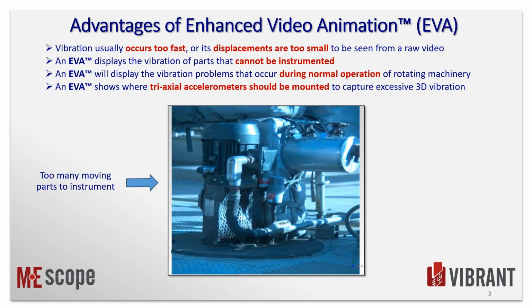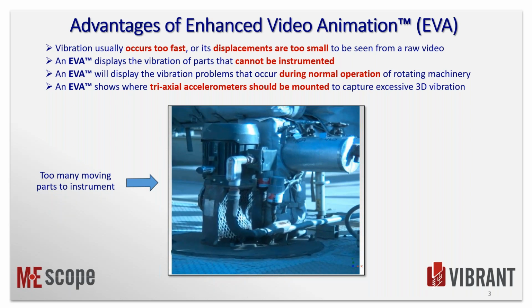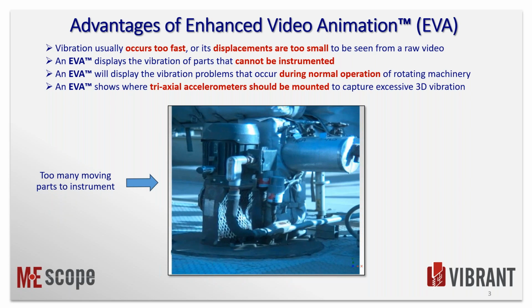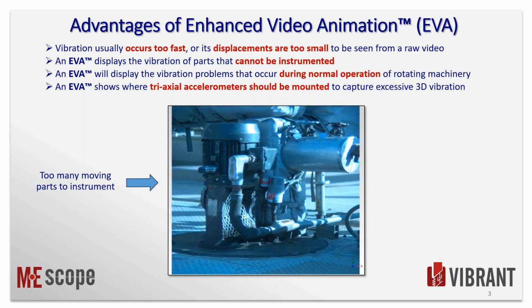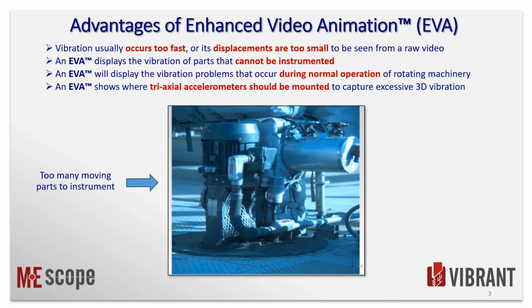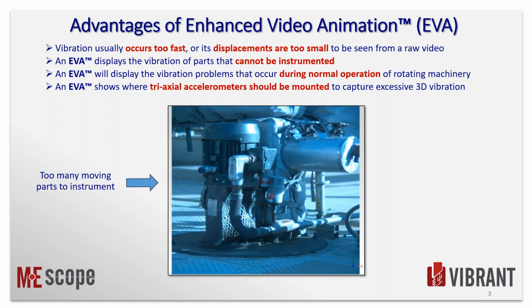And I'll talk a lot about ODS, operating deflection shape. What we mean by that is as soon as I have motion at two or more points and directions, we call them degrees of freedom, on any vibrating test article, we call that an ODS, because now we have a measure of the relative magnitude and the phase between two or more points on the structure. So we call that an ODS.